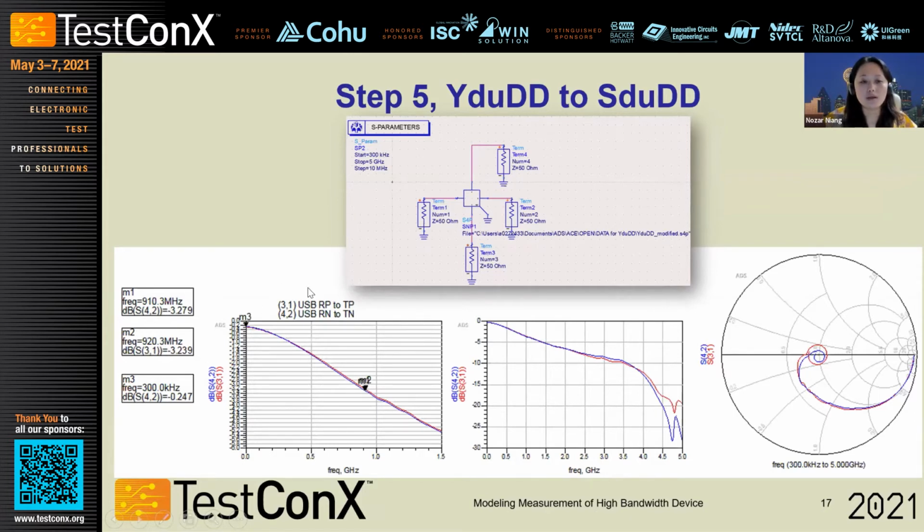At this stage, we are seeing that my device performance is past the spec, but it wasn't what design was telling us. It's supposed to be around 1 gigahertz, and we are seeing around 70 megahertz loss in the design that we couldn't account for. From that, we are doing some study measuring 2 traces just to make sure that our stack up information of the layout traces simulation versus the actual measurement, without including any device performance and so on.